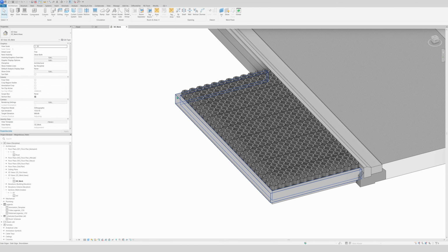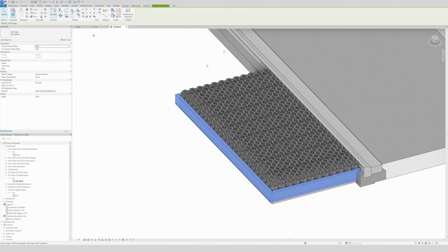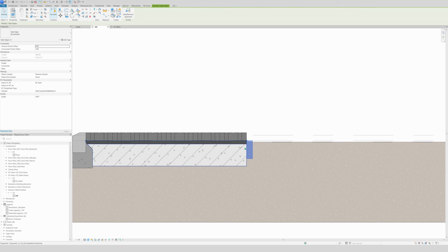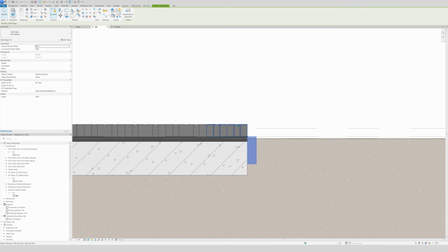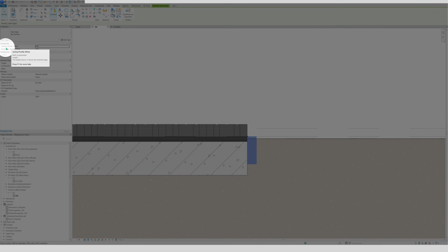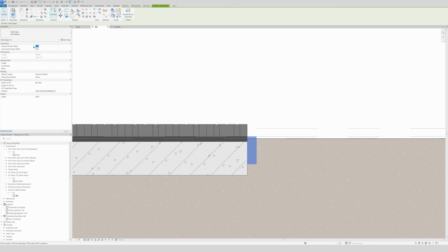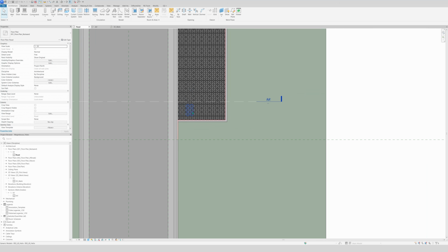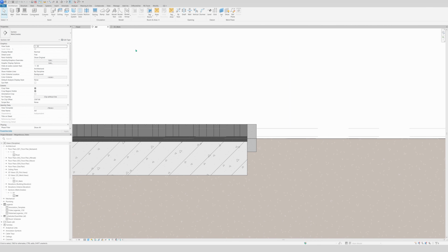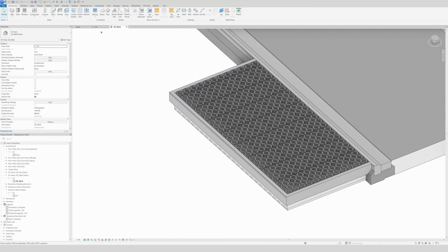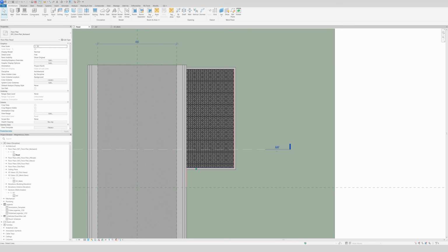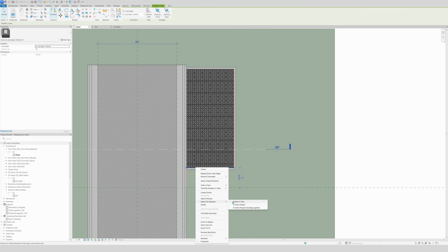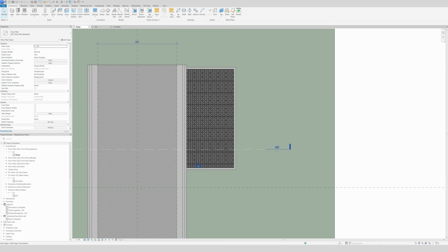So we're gonna select the curb. We go to the section, and then you see it needs to be right at the same place. So how do we change that? Very easy. Right here above we can put an offset, vertical or horizontal. We need a vertical one, and the vertical is the thickness of the stones, and this is 12. And boom, there you have your parking. Very nice. Voila. Now we're gonna get rid of the detail lines, select all instances visible in view, delete them, right.